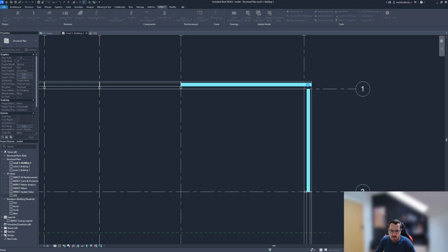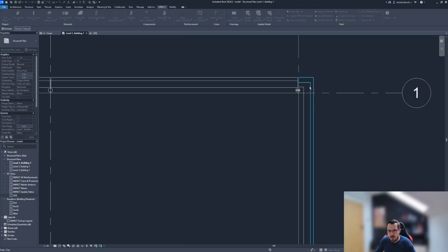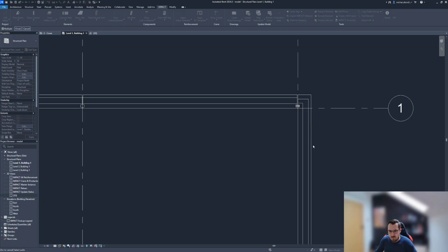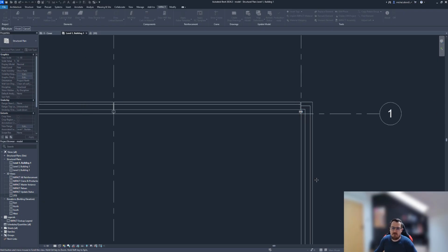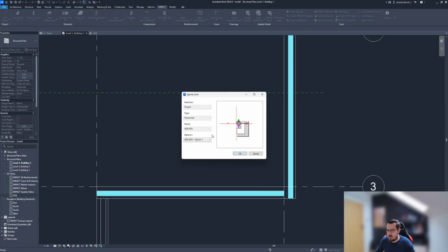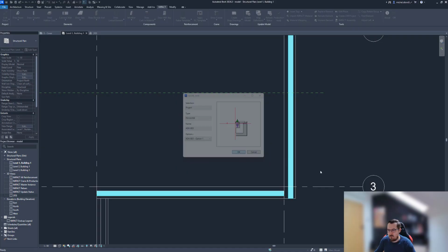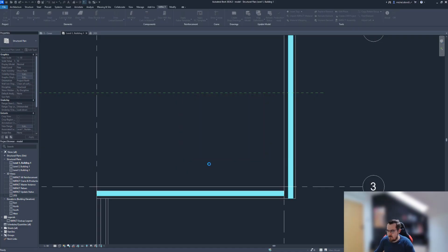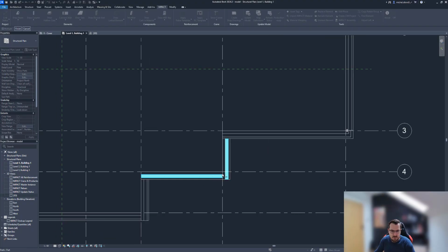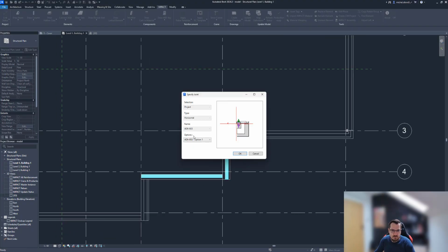And you see now the orientation of the walls will be changed, or rather not the orientation, but rather the end. The wall on the top has been shortened, and the wall on the bottom has been extended to apply for that corner definition that I defined. And I can just quickly go over and do the same thing for the external corners, basically like that, finish.